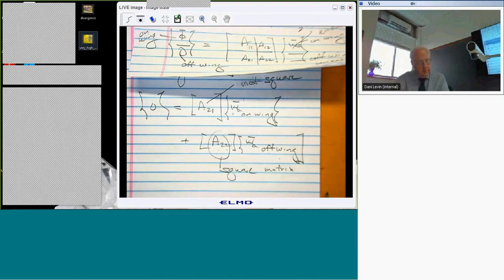I'm at this point, and I'm in the plane z equals 0, and I have the Mach lines like this. As the Mach number goes to 1, the Mach lines become vertical and parallel to the y-axis. So the boxes go out to infinity, even in supersonic flow, as the Mach number approaches 1. But then when you go subsonic, it's everywhere, right?